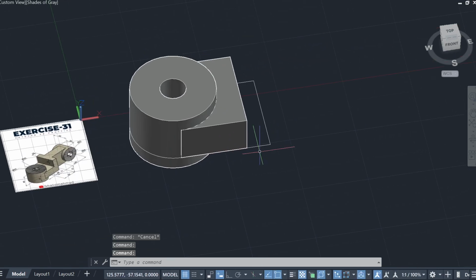Right? So again, yung videos na sinend ko sa inyo from before, it teaches you how to use yung press pull command natin, and it also teaches you, especially yung second video na sinend ko sa inyo, which is very important, yung coordinate system, no. Again, the coordinate system in AutoCAD always works on, or most of the tools work on, the XY plane. So usually you draw something on the XY plane and you pull it upwards on the Z plane.